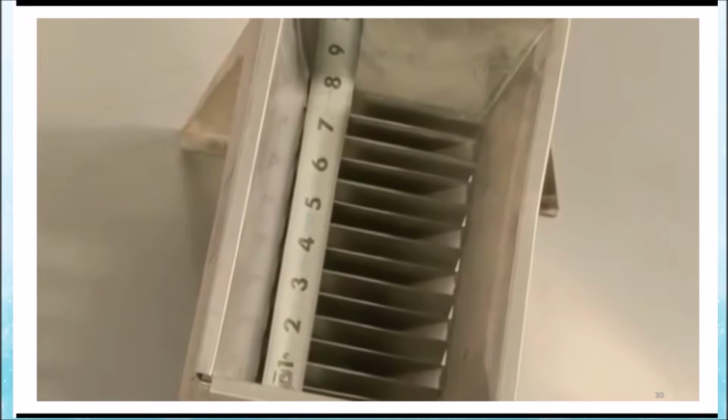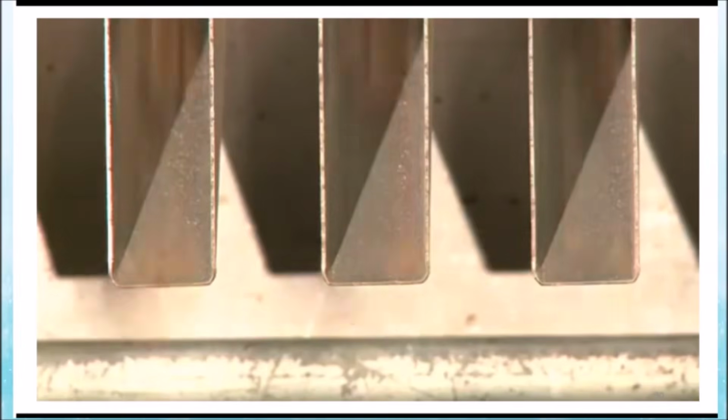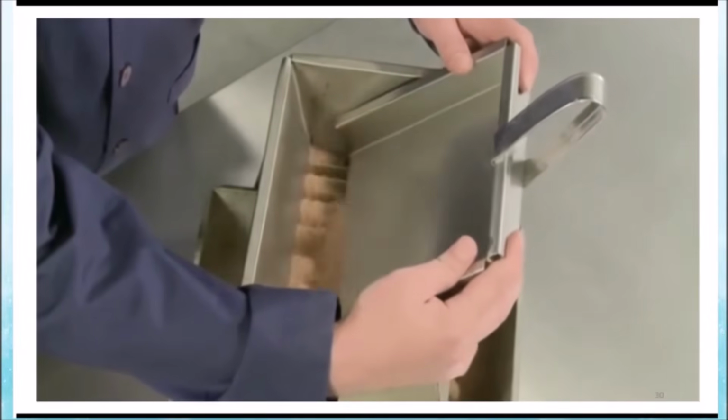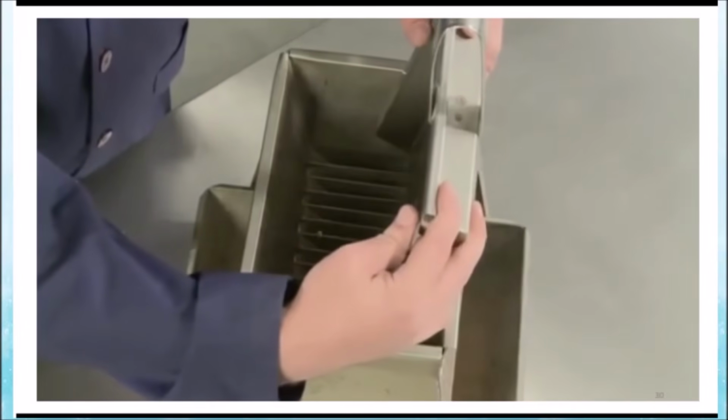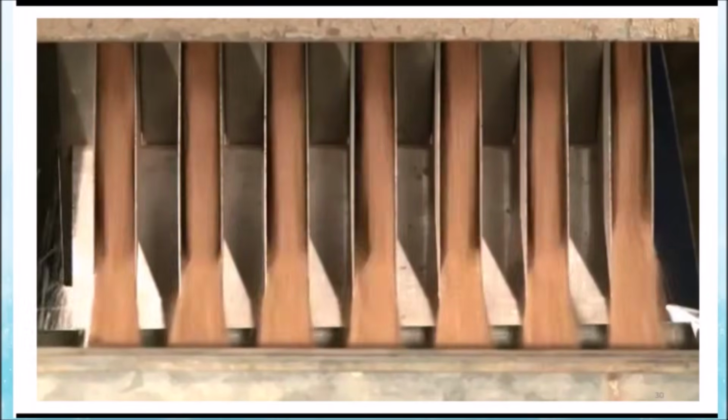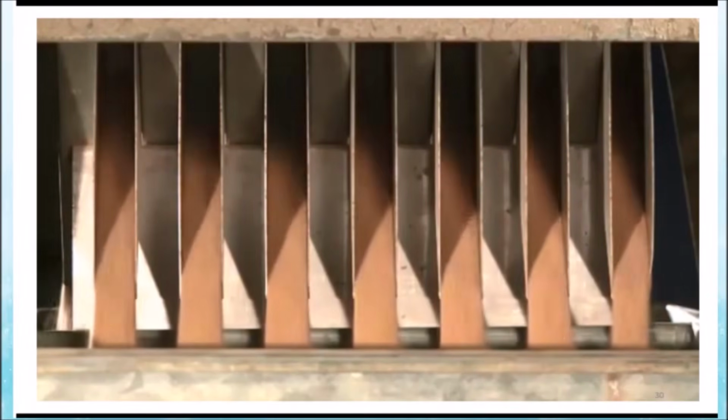The chutes may be no wider than 3/4 of an inch, but must be at least 50% larger than the largest particles in the sample. The hopper shall have a width that is equal to or slightly less than the overall width of the chute assembly. The receptacles must catch the entire discharge from the chutes.